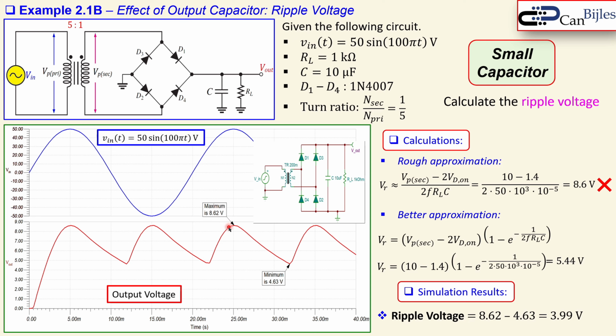The actual situation is that this peak maximum and the minimum value is not a half of the period, but is smaller. And again, that needs to be determined very accurately, but first order approximation will do the job here, but you need to be aware of the error you make by taking only 1 over 2f, which is not correct because the period is smaller. Then you have this approximation and you will see that this is 1.45 volts off.